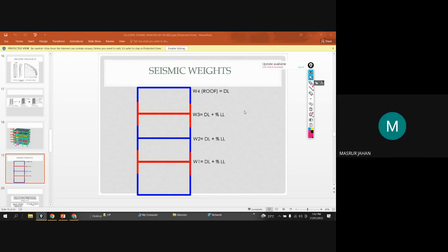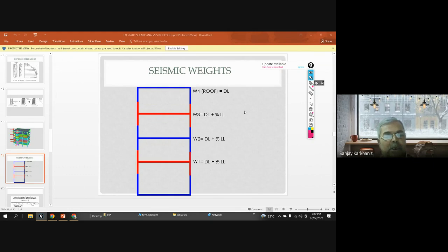We are not calculating any reactions. When you are calculating reactions, only then you can say that the load above will get transferred below through the columns. It is not transferred on the floor. It is transferred on the columns only. Make it clear. If you have a 70-story structure, that doesn't mean the floor at first floor or plinth is supporting all the load above.